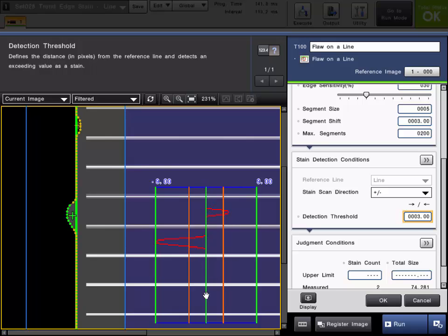This green down the middle is the reference model line. These are the actual detected points, and this line here in orange at this moment is our detection threshold. So you can see those points passed that threshold and they became detected points. And you can adjust that threshold as needed according to the application. But it looks like the default level of 3 is okay for us.